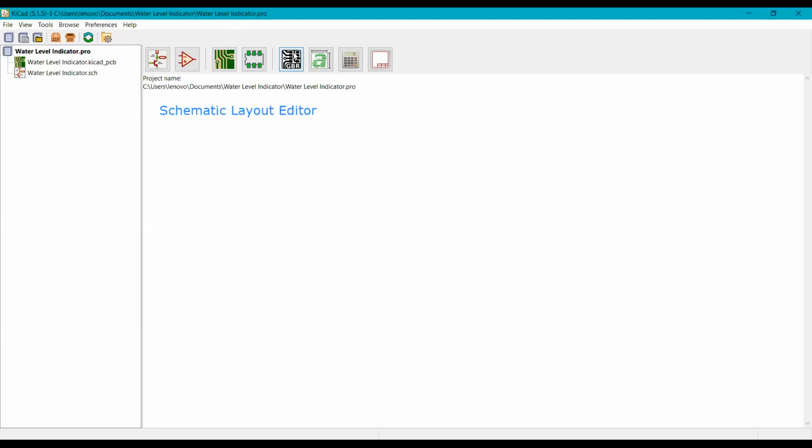This is the file in which you can see your PCB in a 3D mode or in layer by layer sections. Like if you have a 4-layered PCB, then you can separate those layers by creating the Gerber file. And you will not send the .pro, not the .sch, or not the .kicad_pcb to the manufacturer. You will always have to send the Gerber file to the manufacturer. If you want to get your PCB manufactured, then they will ask where is your Gerber file.